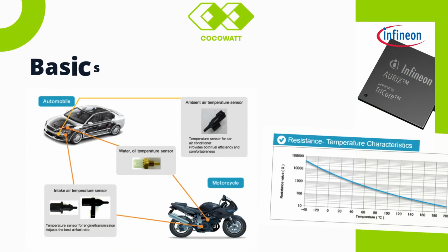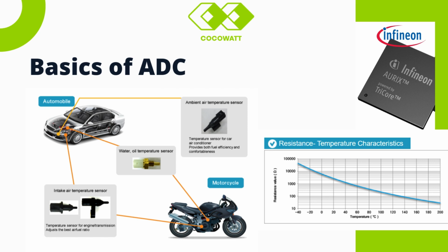Temperature sensors like the engine coolant temperature sensor or intake air temperature sensor use thermistors. So here what happens is, when temperature is increasing, the resistance gets reduced.